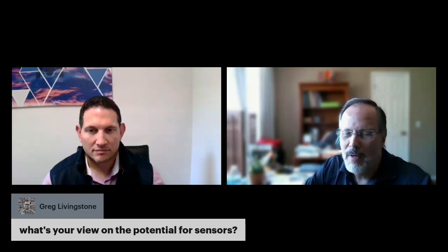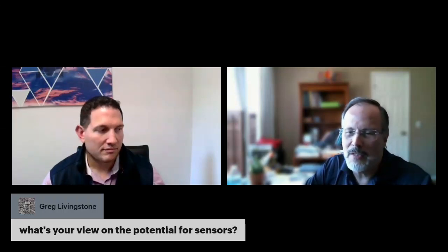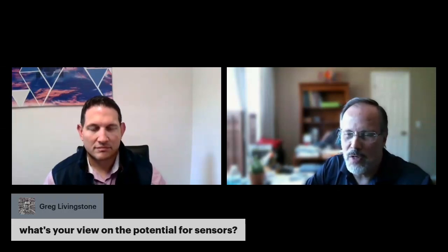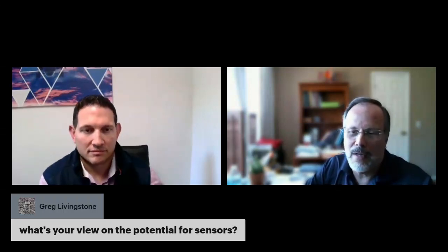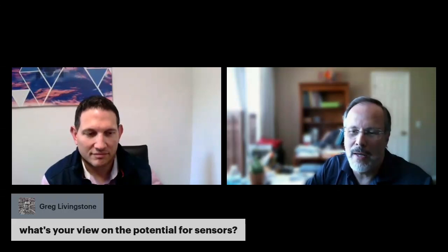And the suggestion is that these online sensors for continuous monitoring should be for really significant critical equipment we want to monitor perfectly, like in power generation plants, turbines, or large compressors in pumping stations and things like that. This is still ongoing, and certainly they are really valuable, but still do not replace a good quality oil analysis.